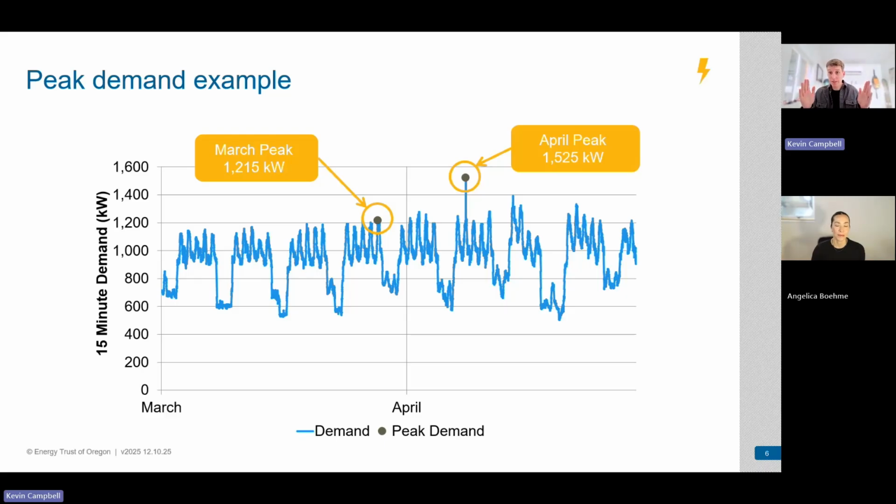That is a great example because those furnaces, when they're warming up, are going to take longer than 15 minutes, right? So if you kick them all on, then in that 15-minute window, you have every single furnace trying to warm up at the same time. If you stagger those, you're absolutely right, you'll bring that demand charge down a lot. That's a great example. Thanks for sharing, Angelica.